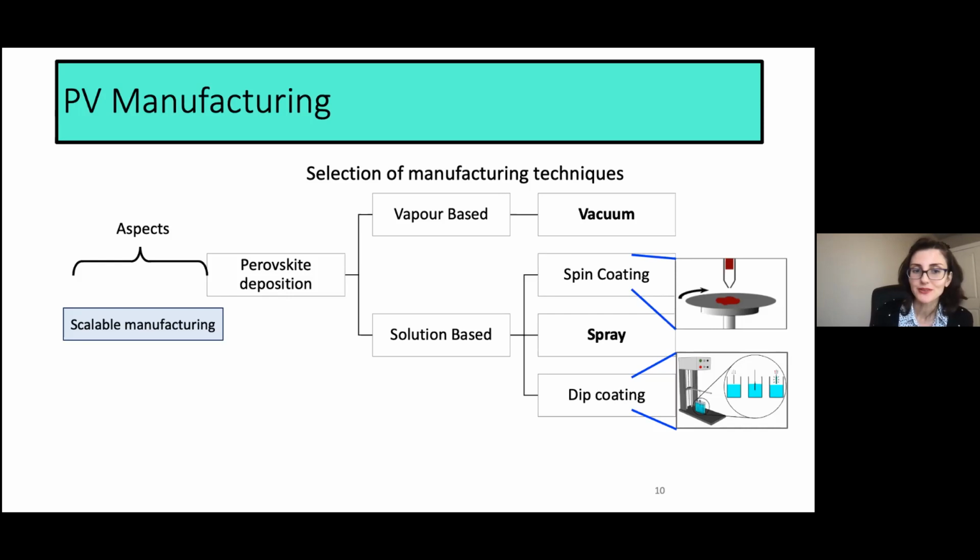So industry wouldn't like that, and we removed that. Dip coating methods are again a good method in lab-scale conditions, but in large-scale production, you're going to waste a lot of materials, you're going to contaminate some of them, then you have to recycle your chemicals, and that wouldn't be very practical from an industrial perspective.